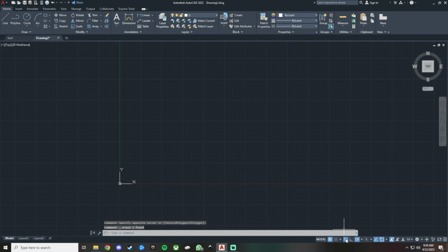If I turn dynamic input on, you will notice that when I select the object that I want to draw, we now have these blocks that are giving us information. It's saying specify first point, and then it's showing me the point on the page where I'm going to start drawing, which really doesn't matter at all. Once I click the line, I now have the option to give the length as well as the angle. So let's say I want the line to be 10 millimeters long.